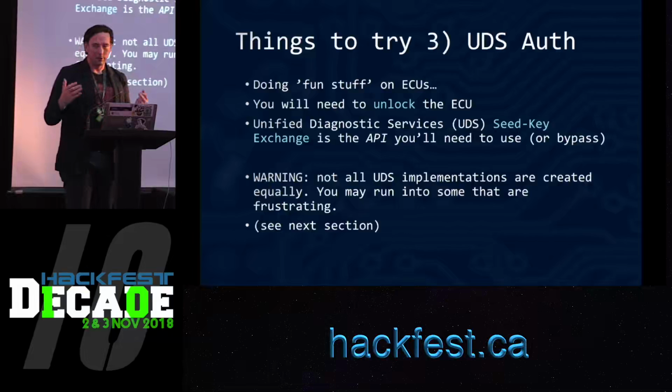So really the point of this talk is that when you open up a flat binary file, and what I'm looking at here now is Ford's open source firmware for the OpenXC. It's an ARM binary file. We're going to talk about this at length. But I'm going to try to analyze it. And it says it made some flags, but it really didn't. I can't seek to main. This is a flat binary file. It doesn't know main. There's no symbol information here. So really, when you're using Radare to reverse engineer a flat binary file, the best you can get is Clippy's help. And this is a fun Easter egg. You can do $!E and it'll show you Clippy in case you feel lonely while you're reversing. Yeah, might come in handy someday.